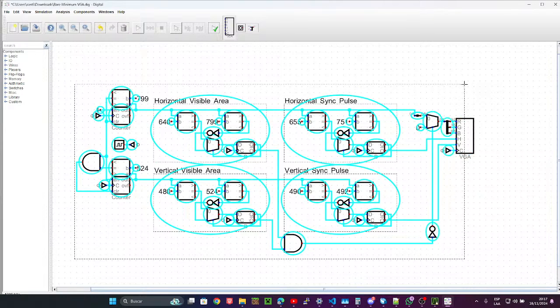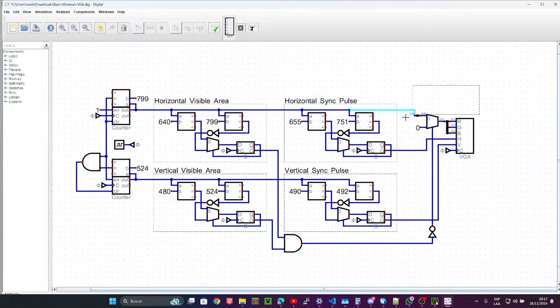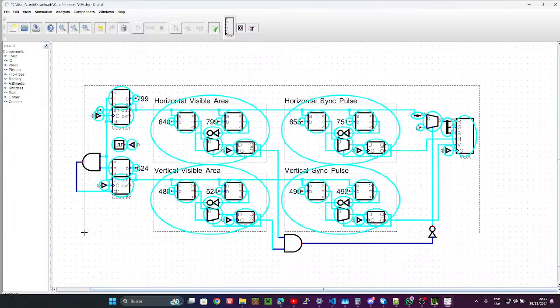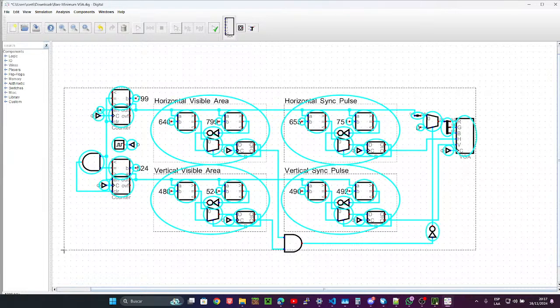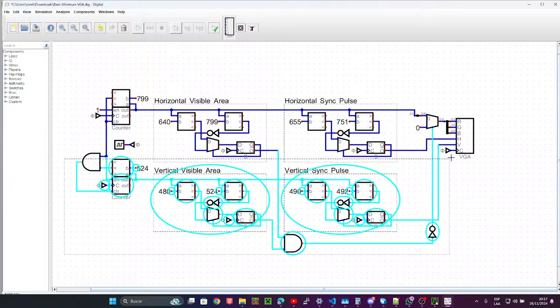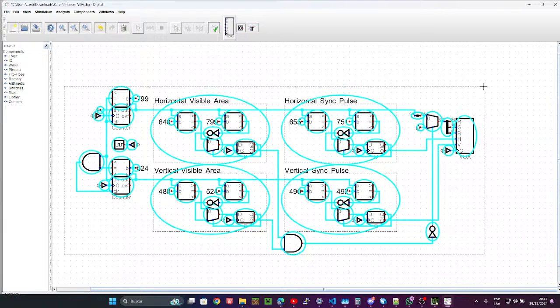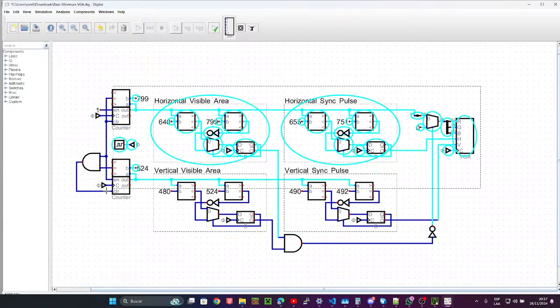An old one, because this is VGA. This is the circuit that generates your video signal from video memory. This is literally the display controller, not the GPU. The GPU works on the video memory. It's between video memory and the CPU. Between video memory and your output is this circuit.